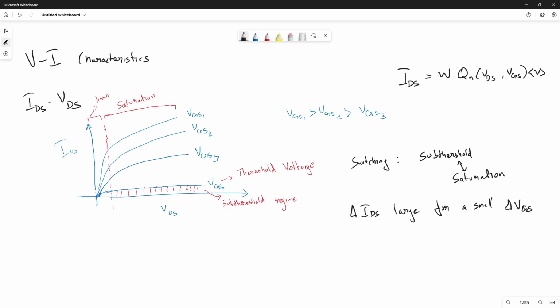So ultimately, when I'm looking at the band structure and all these things, if I want to use my MOSFET in integrated circuits, most of the transistors in an integrated circuit act as switches. So since they are acting as switches, I will need this kind of a behavior. So if you are given a bunch of IDS, VGS, and you want to analyze the switching property of a device, the curve that you're supposed to look at is not the IDS VDS, but the IDS VGS. So that brings us to the next curve that we shall see, that is the IDS VGS relation.